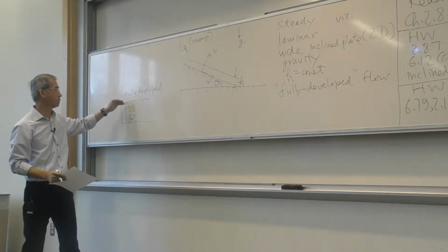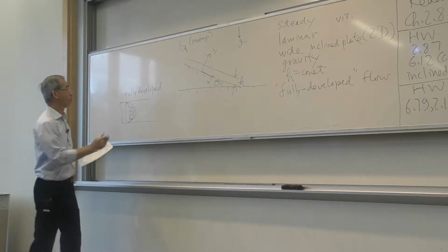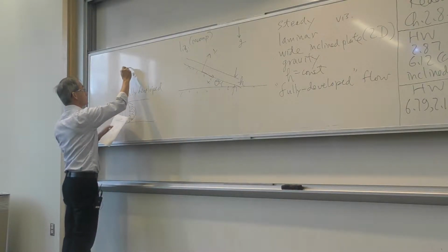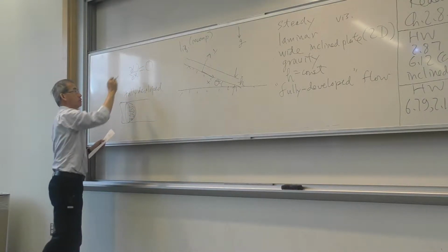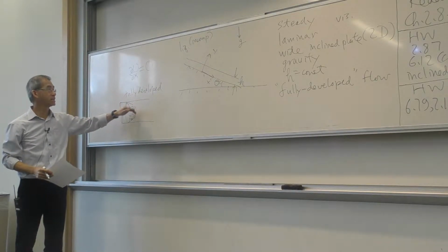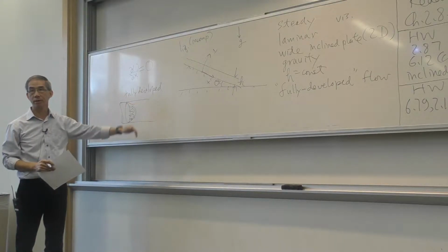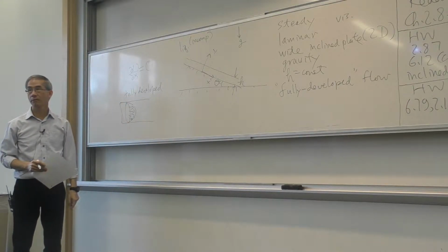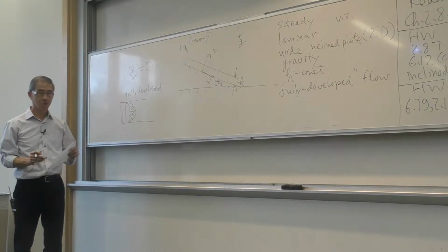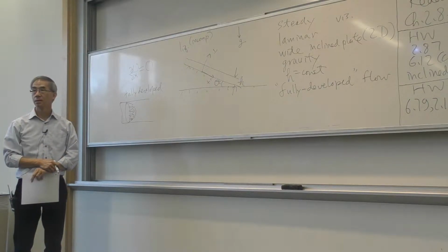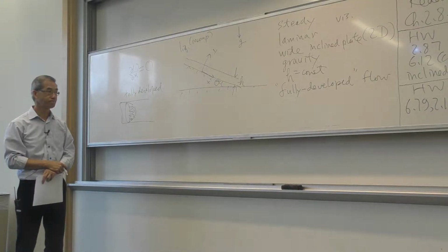It's already reached a plateau, that the flow velocity profile, or specifically any variable to be determined with respect to distance x is 0. It's not changing with the streamwise direction, and hence the word fully developed. And that's very important for how we can simplify our Navier-Stokes equation. Do you understand this implication? Fully developed. Okay?